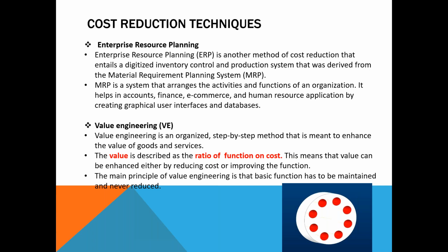One more example I can give you of value engineering. Those of you from forging industries will realize that steel mills supply steel with sulfur between 0.02% and 0.04%. Now, if the sulfur is maintained at a higher level, we require it to be maintained at a lower level of 0.014%. Why? To prevent sulfur streaks from appearing in a linear form. When this steel is rolled, these sulfur streaks come out on the surface and you will find a crack. So you find raw material cracks on this.